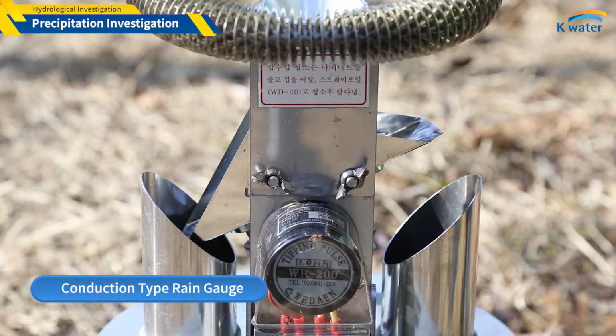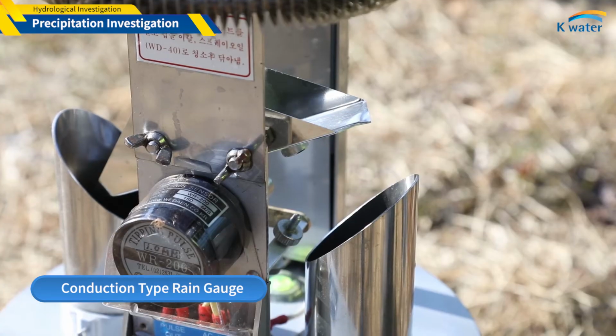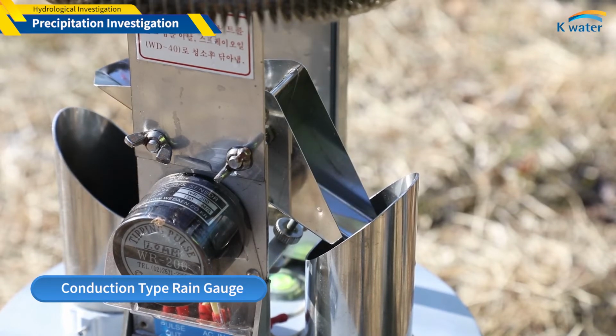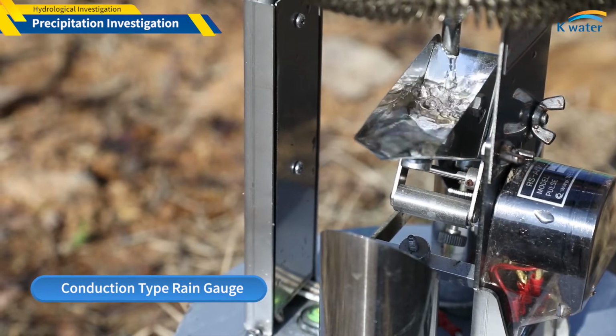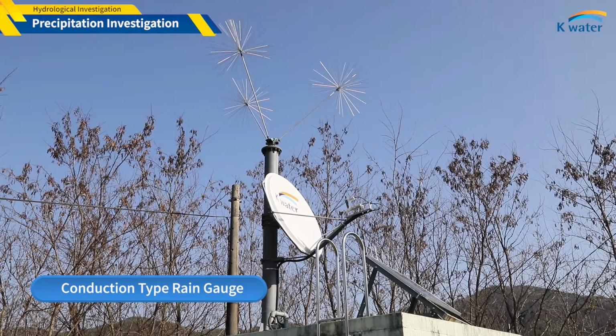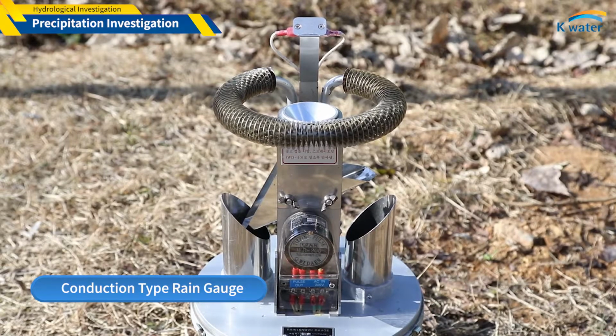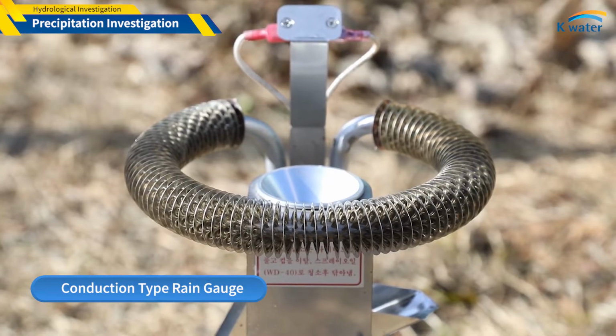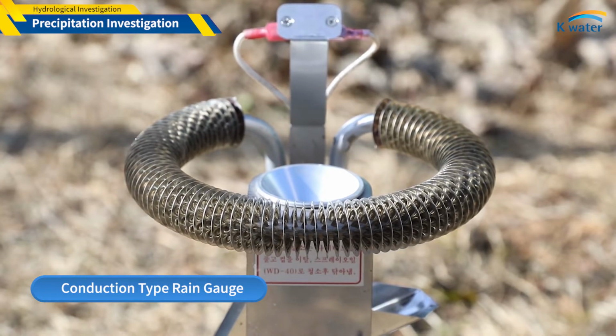The principle of the conduction type rain gauge is as follows. When a certain amount of rainwater is collected in the collection cup through the water inlet, the cup tilts and drains into the reservoir, and the amount of precipitation is recorded according to the number of conductions. Recent conduction-type devices have built-in heating wires that melt snowdrifts to measure snowfall during the winter.